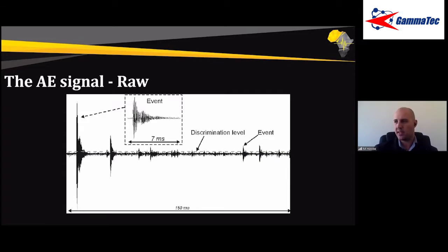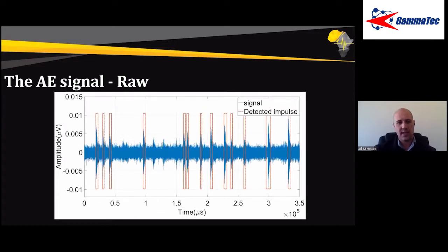Now, this is extremely time consuming. If you're looking at a corrosion test, for example, you have 180,000 of these hits, as we call them, or events, in an hour-long period. Luckily, with the introduction of computing, we can detect these points or events. So we set a threshold, and every time the signal crosses that, we have a look at that, and we can obtain some information. This is the hit-based architecture, which is used extensively in most forms of acoustic emission, except